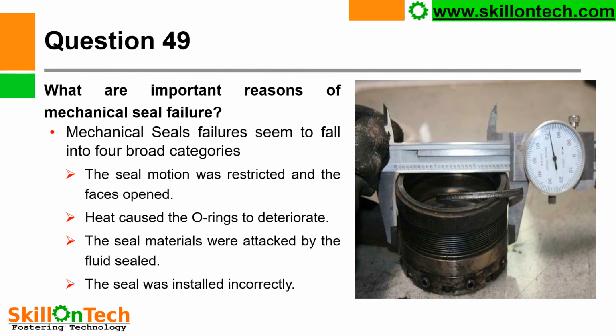O-rings are made of rubber. O-rings are not suitable for very high temperature. Therefore, leakage can start from mechanical seal. The seal material was attacked by the fluid sealed. The fluid which is used for sealing of the seal, or a fluid which is handled by the pump, if of corrosive nature, then they can attack the seal material, and seal material can corrode or have pittings. So that can also lead to failure of mechanical seal.